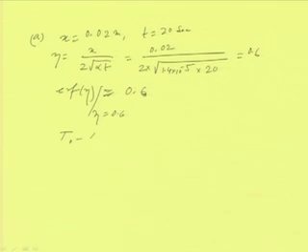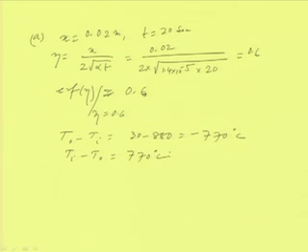We also know that T0 minus Ti is equal to 30 minus 800, which is equal to minus 770 degree centigrade, and so Ti minus T0 is equal to 770 degree centigrade. So, now just putting the values, we know that T minus Ti we have to calculate, and that should be equal to T0 minus Ti into 1 minus erf of eta.